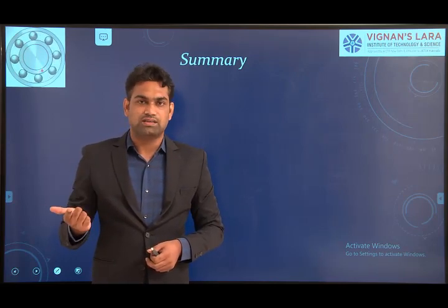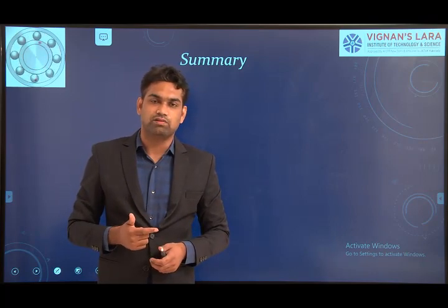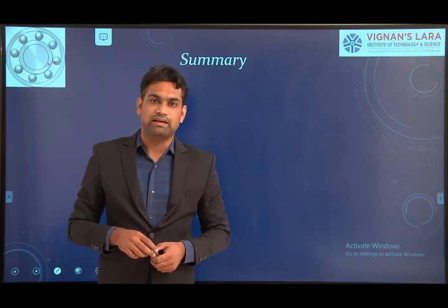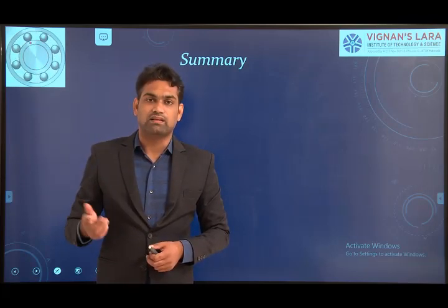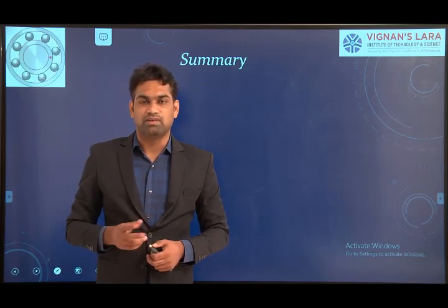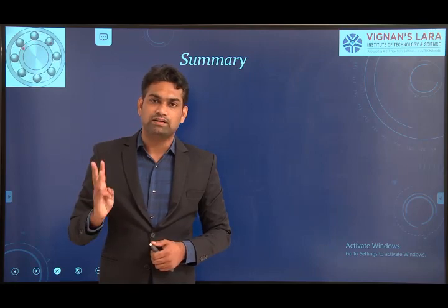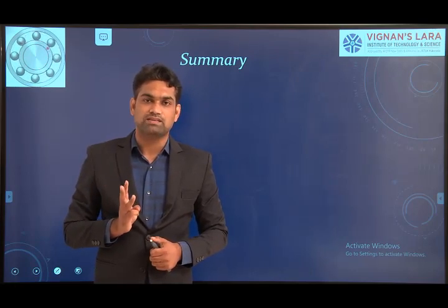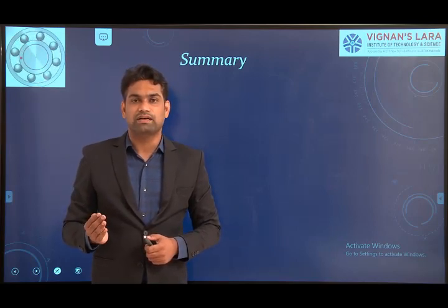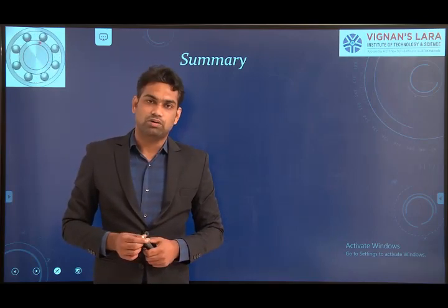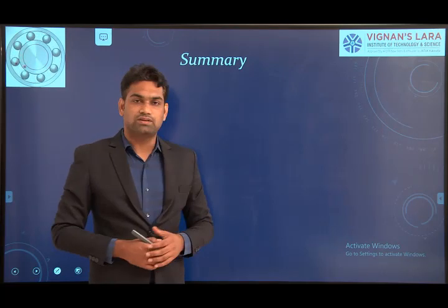The second step is calculating the life, that is, the life in million revolutions. If they give life at 90 directly, it is okay. If it is a life other than L90, such as L99, you need to apply the Weibull equation so that you can calculate the life at 90% reliability. Finally, the third step is to calculate the dynamic load capacity C using the load life relation. Using that dynamic load capacity, we select the suitable type of bearing for our given application. Clear? So that we can finish unit number 1.